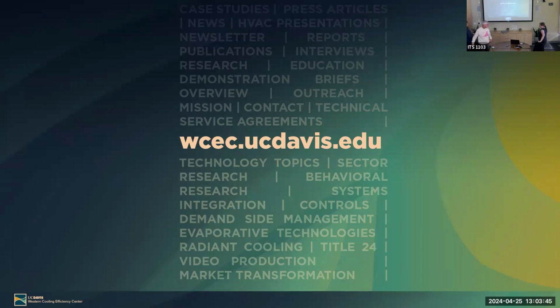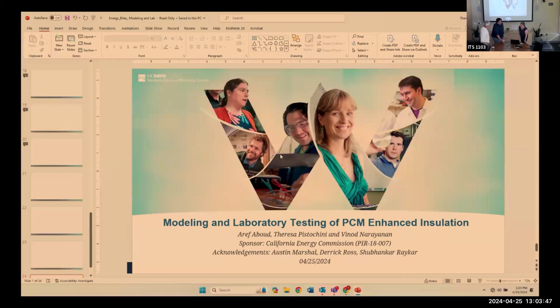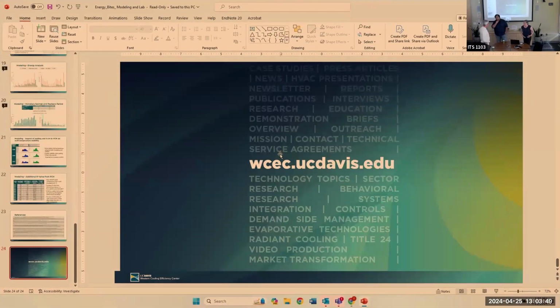So if your recommendation is to go from 6-inch studs to 4-inch studs with the addition of PCM, there's one manufacturer of PCM that sells in the state. And that's for only new builds, right? Correct, yeah. Is there any kind of estimated cost savings to it? Is that a significant cost savings? I think the 6-inch studs should cost more to the builder. I think the argument is that there's the same amount of lumber, it's just because you space your studs 24 inches apart.